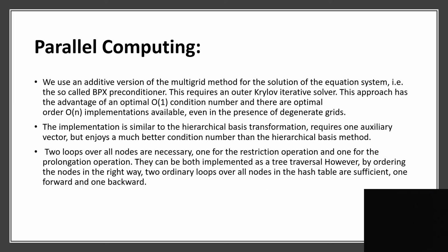Parallel computing. We use an additive version of the multigrid method for the solution of the equation system, the so-called BPX preconditioner. This requires an outer Krylov iterative solver.